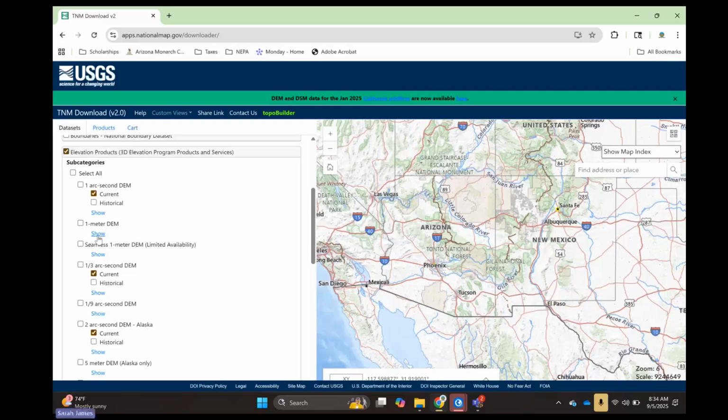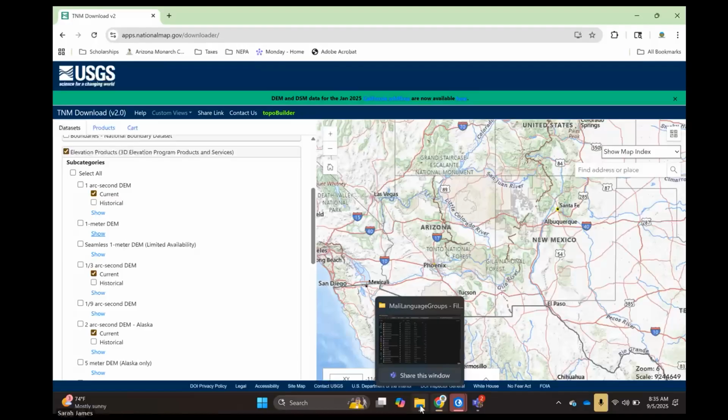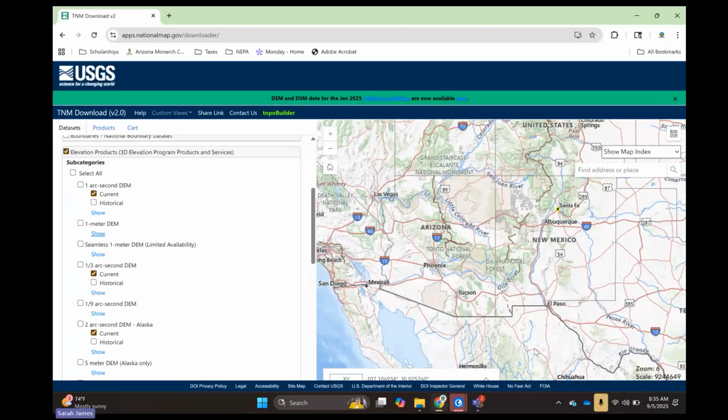Sarah, real quick, can I interrupt you? We have a question. Why does the UTM coordinates show 12S on the Garmins for Arizona? I tried changing it to 12 North, but received errors in the past. I would check the coordinate system it's actually using. It's probably pulling from one of the other ones. It's probably not wrong because it's a GPS tracking you, but it's probably using a different coordinate system than the one that I showed that was NAD 83 North. It might be one of the other geographic ones, or something like that is happening. Sorry that I don't have more info though. Without seeing it, I can't tell you.